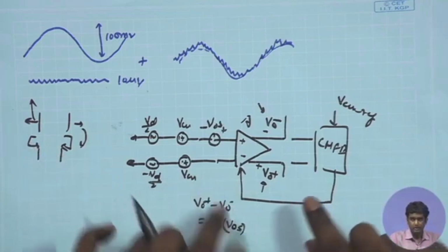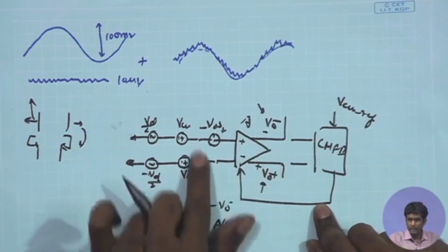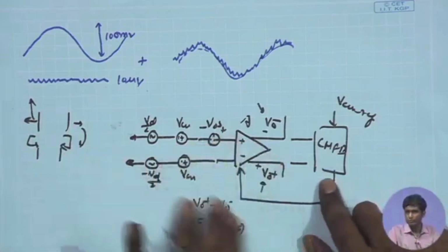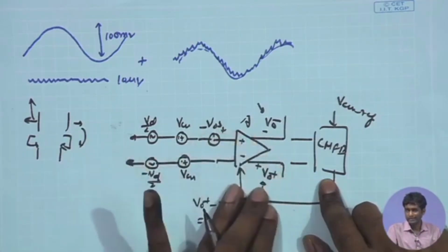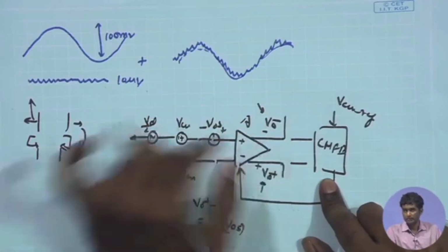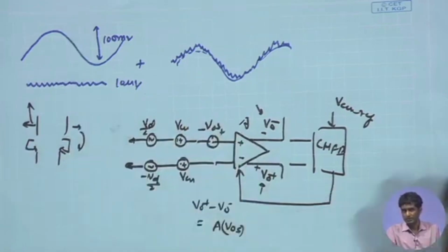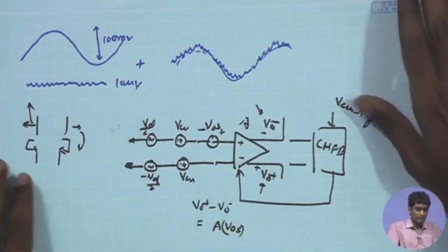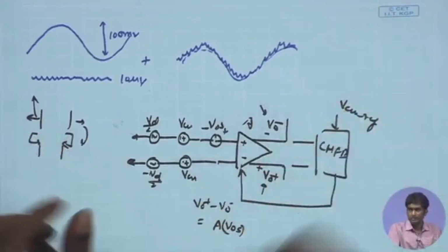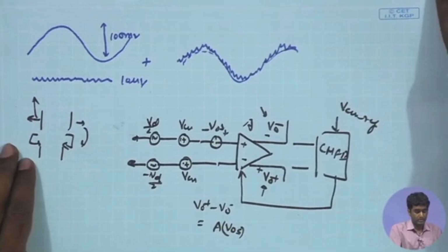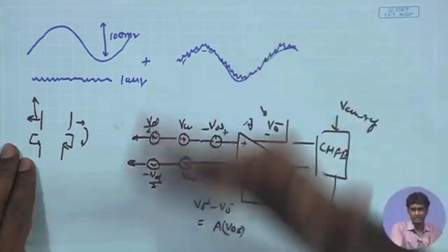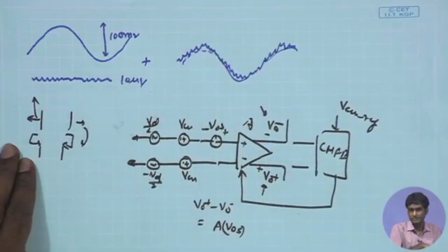Therefore, independent control of the output common mode and input common mode can create these issues, and if we do that, once again we may have to go for auto zeroing and those kinds of techniques to take care of this offset voltage, so that the offset is compensated and we are able to cancel it out. But once again, if you apply auto zeroing in the front end amplifier itself and you have so much switching noise coming from those transistors, they can once again aggravate the noise considerations and make the noise worse.